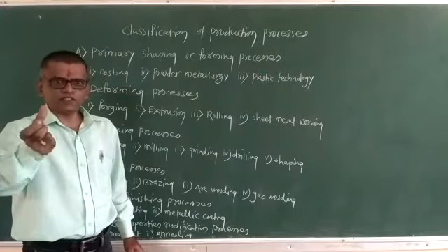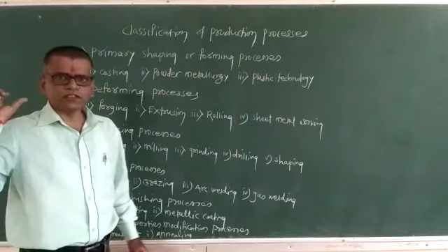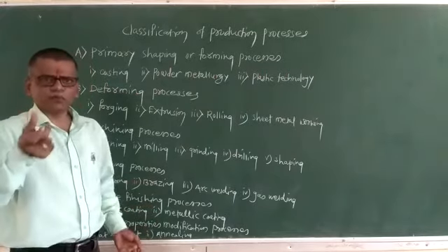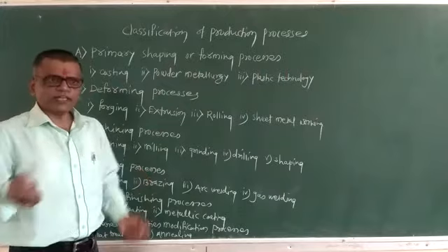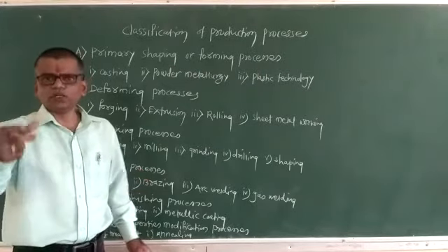If some drilling operation is required, then the object is heated below sintering temperature, and then the drilling operation is carried out, so that the object has enough strength to handle the machining operation.